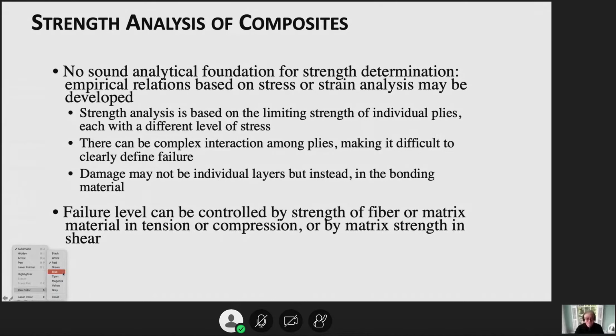In fact, the reason why we like composites is this fuzziness, that the fiber is so small that there is not enough room for sometimes micro-level cracks happening within the fibers. And when they happen, it happens in such a small scale that stresses recover right away around the fiber break. And you don't lose strength by failing one single fiber out of millions and millions of fibers.